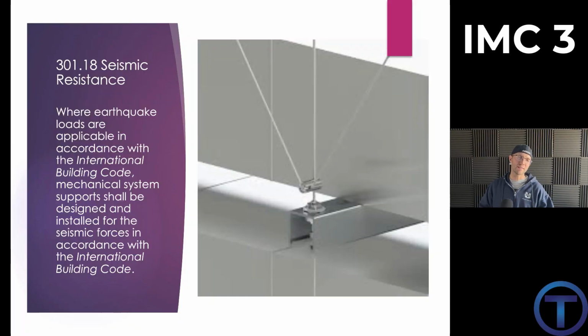301.18 talks about seismic resistance. And it says several times in there, look over at the International Building Code. Any of these seismic supports that are installed on mechanical systems would have to meet the International Building Code standards.